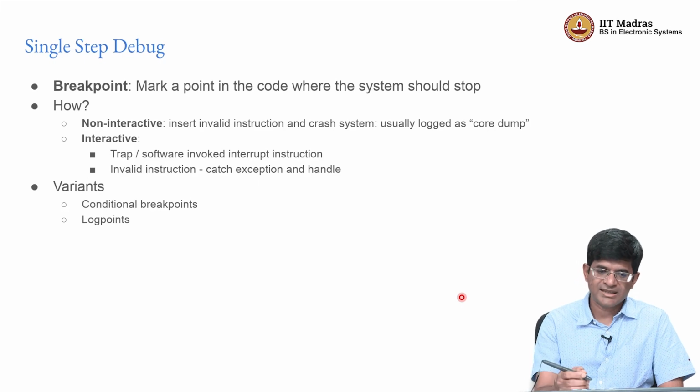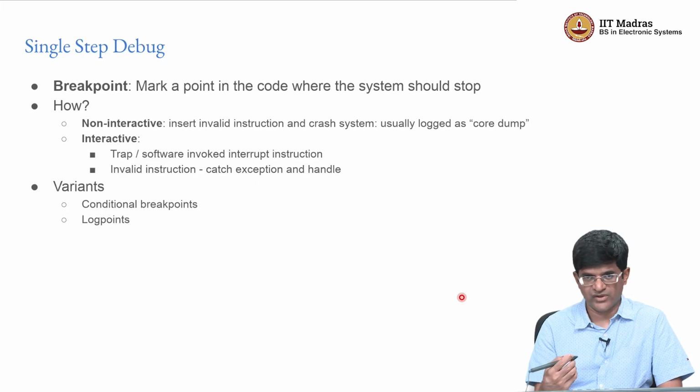So what that means is that the debugger, which is itself a program, most likely is going to run on your host computer. What do I mean by a host computer? As we discussed earlier, most embedded systems are cross-compiled, meaning that you are probably working on a PC, it could be a Windows PC, it could be a Linux PC, writing code and compiling it, but the output that you generate is not going to run on the Windows or Linux PC that you have, it's going to run on your microcontroller.